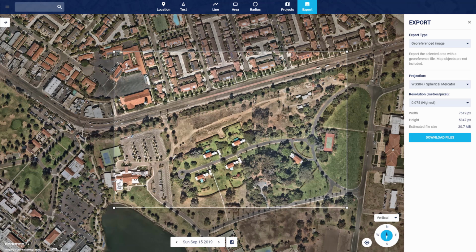Say you have established a shared coordinate system in your Revit file, and you also have a set of aerial images that you want to use to add some information to your site plan. Well, I can show you how to bring in these images so that they're scaled correctly and they're also placed in the right coordinates. Let me show you.